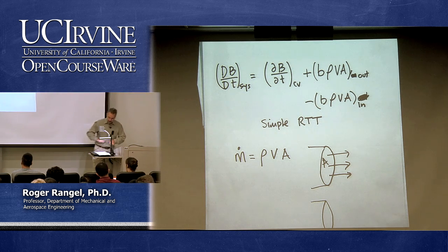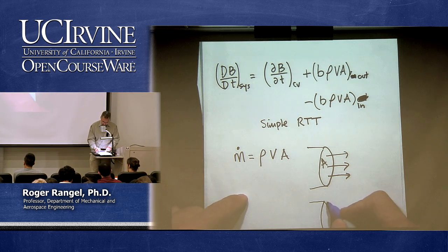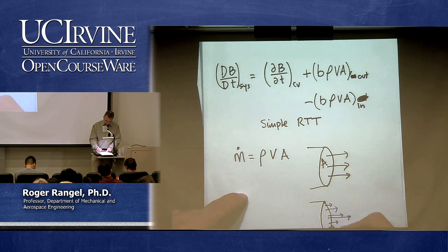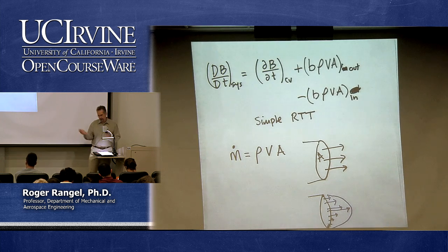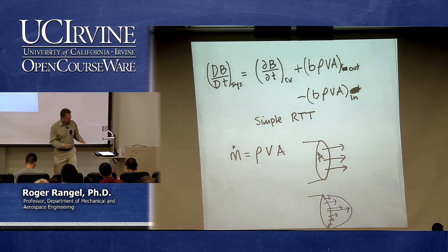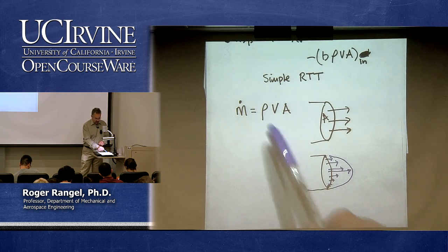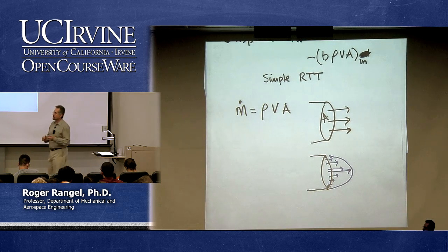Very good. So it'll be something like this. In fact, it'll be 0 at the edges, and then it should get larger, larger, larger. The largest value is at the center, and then less, less, less. So in fact, it'll have some shape like that, if I make a realistic drawing. So when I say that the mass flow rate is rho VA, the question arises, what's that V?